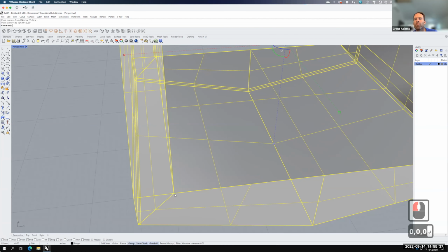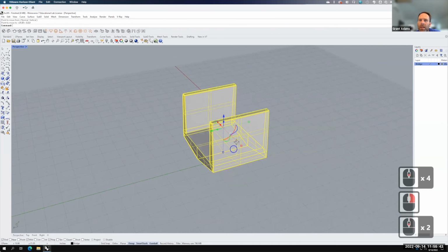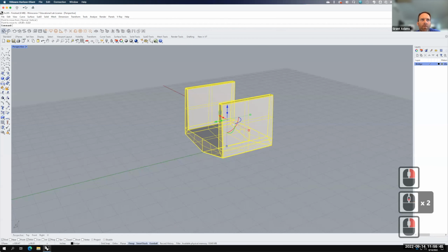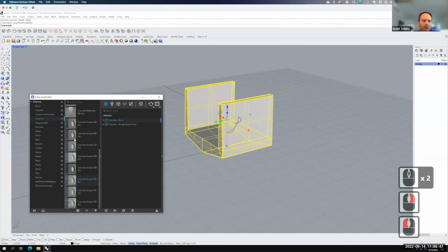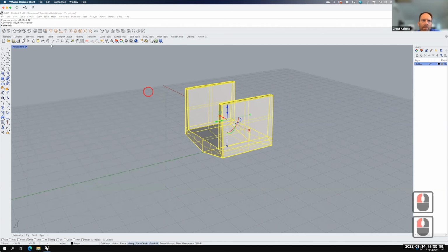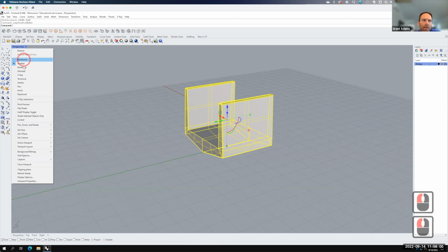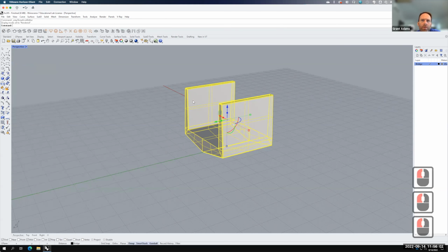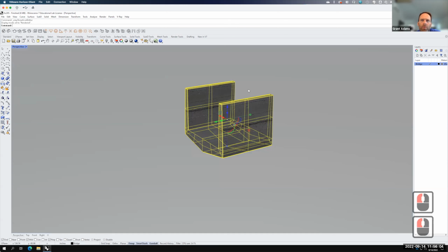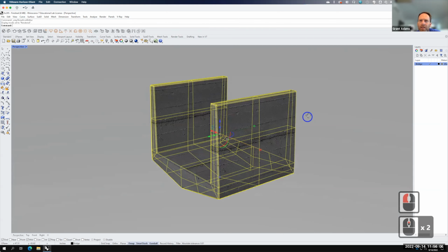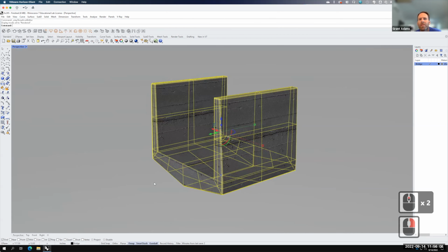So let's make sure our materials have been applied and we like our texture mapping. So let's go into our V-Ray asset editor here. I'm going to work with concrete. Let's go ahead and use that concrete simple. I'm going to apply to the selection. And then let's look at it. So I'll click here and I'll go into rendered mode to take a look at what it looks like. This way I can kind of see my texture mapping. And remember that this is roughly a square. So let's use that to our advantage.